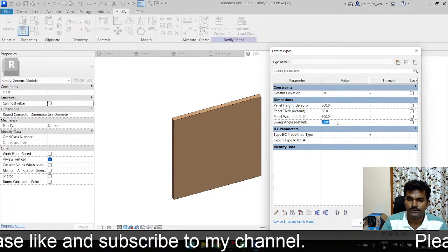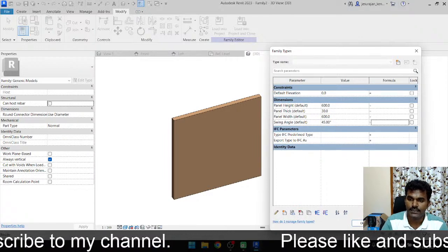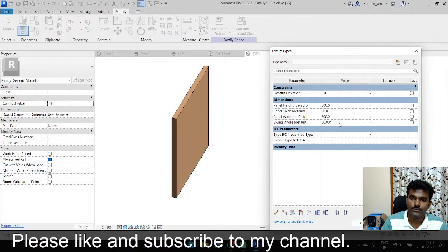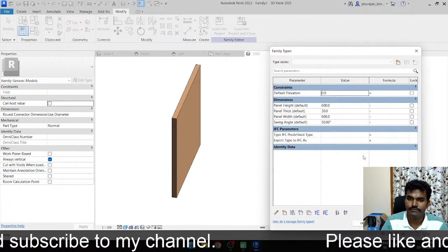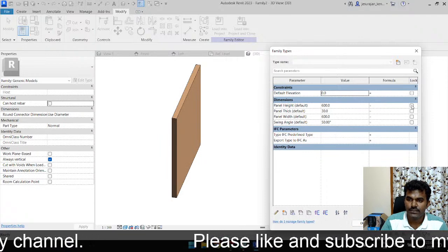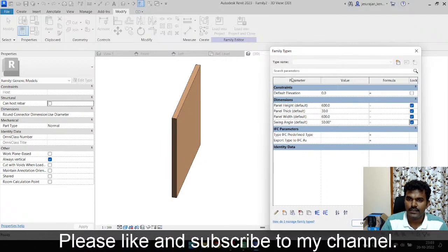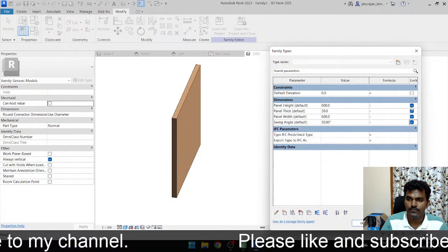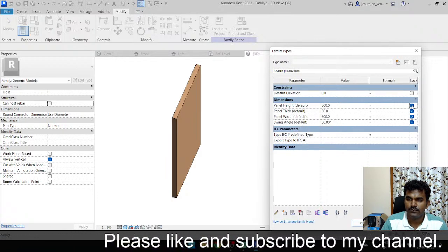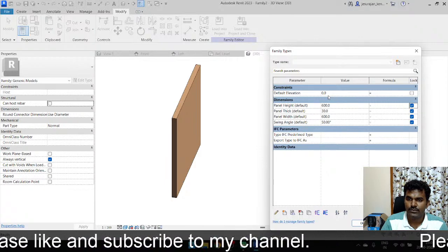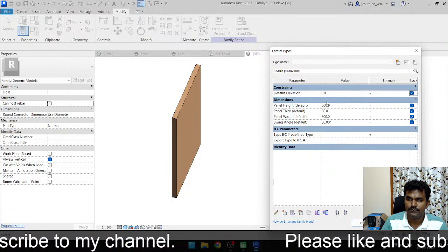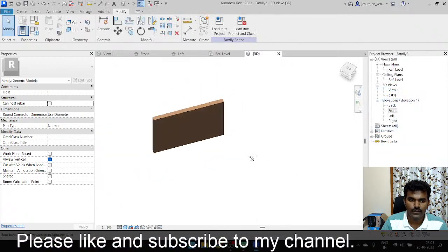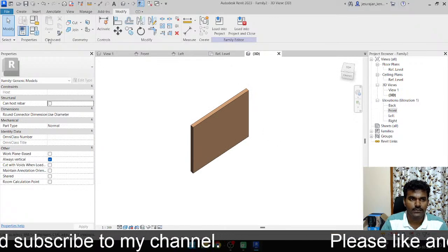And swing angle, if I keep it as 45 degree, and if I apply, you can see this is changing the angle also. Apply. That's what I need. Just lock everything so that we don't change it. Default elevation is going to be 0, and just give okay. So this is my panel. Save it.